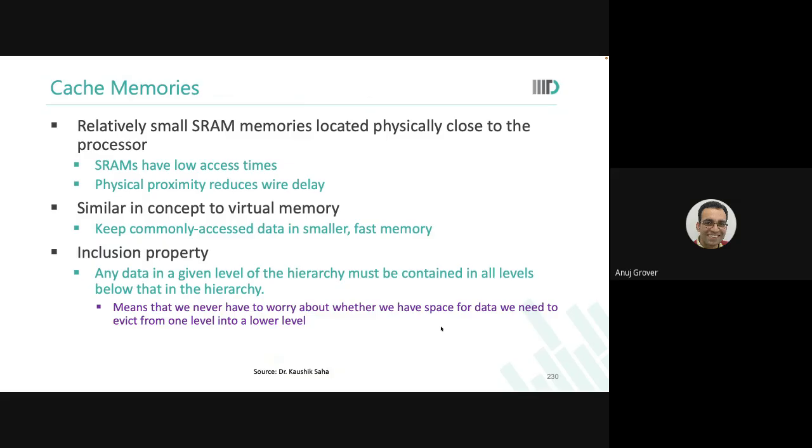It is proximity based. Basically proximity. It is not necessary that a cache memory has to be an SRAM. In fact, there are studies about not just DRAMs, we're also talking about phase change memories or RRAMs or other emerging memory technologies to be used as level 2 or level 3 caches because they are denser than SRAMs, much denser than SRAMs. Is that okay?